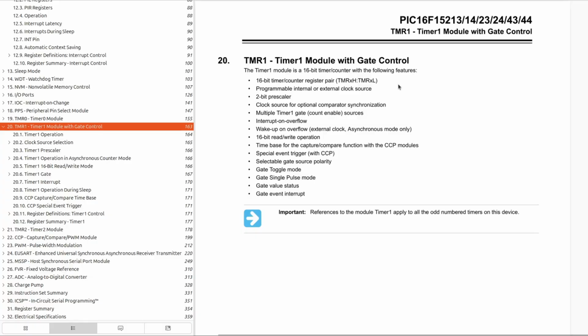timer. And we also identified that the timers are a little bit different. Timer 1 is one of those different timers. It's only got 4 prescalers, 0 postscalers. It cannot be configured to roll over at a specific count, but it's got a few special modes that we're really not going to discuss today.